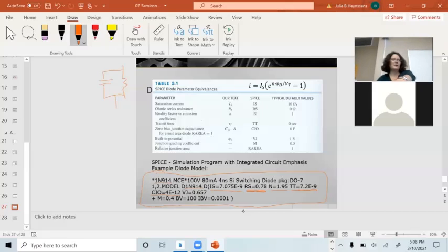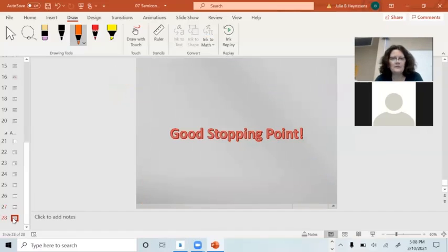Don't ever try to write this on your own unless you're the guy building the new op amp and you have to make the model and make it work. Use other people's work. There's a lot of things that's like GitHub, but it's for electrical engineers. Ultra Librarian is kind of like one of those GitHubs, but it's standardized and it's traceable back to the manufacturer, so you know you're getting a good model. Because if your model's wrong, your whole thing doesn't work.